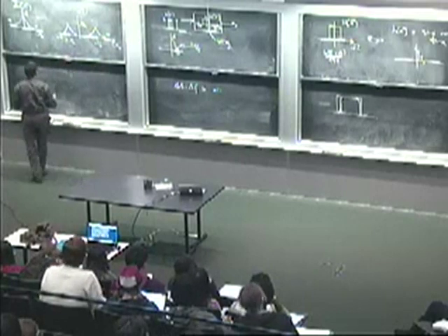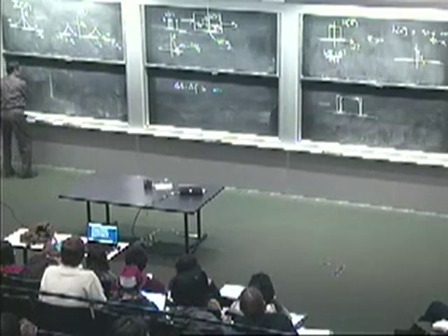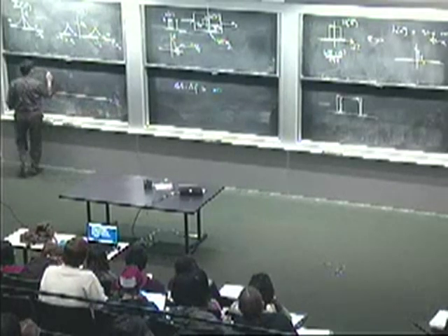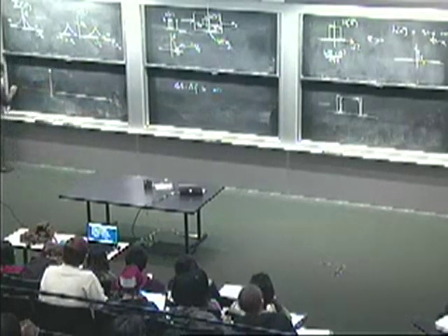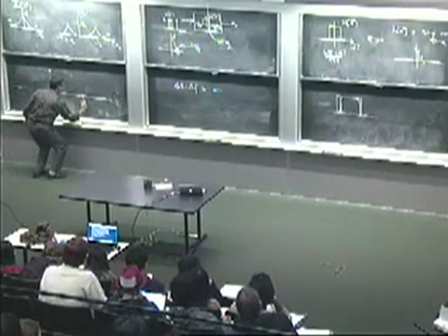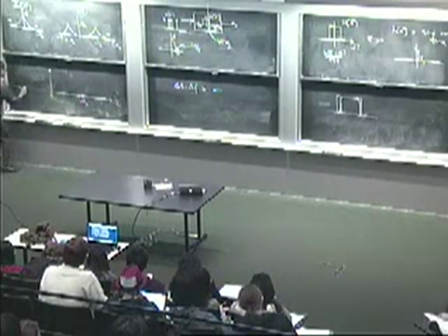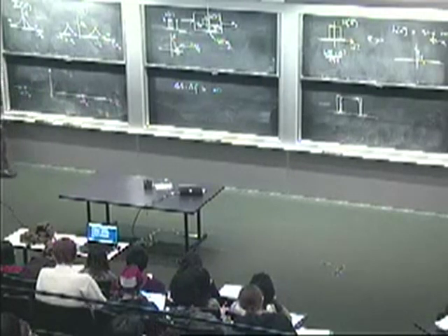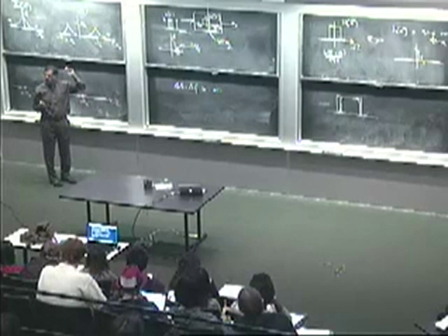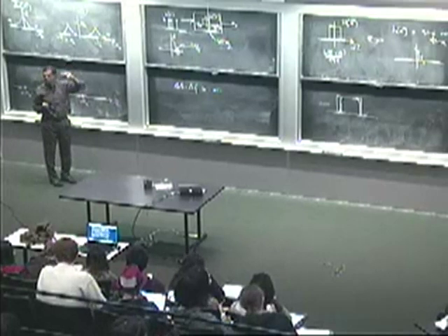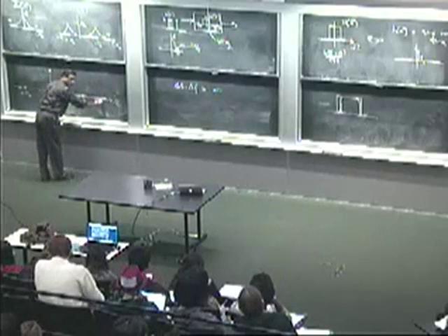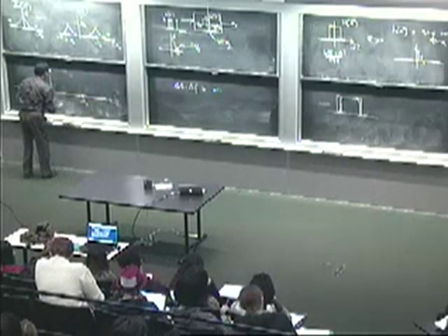And what's that going to do? Well, here's my omega c. Here's my minus omega c. What's coming in is this signal. I'm going to multiply it by cosine omega c. So what does that do in the spectrum? It takes this spectrum and replicates it at omega c.